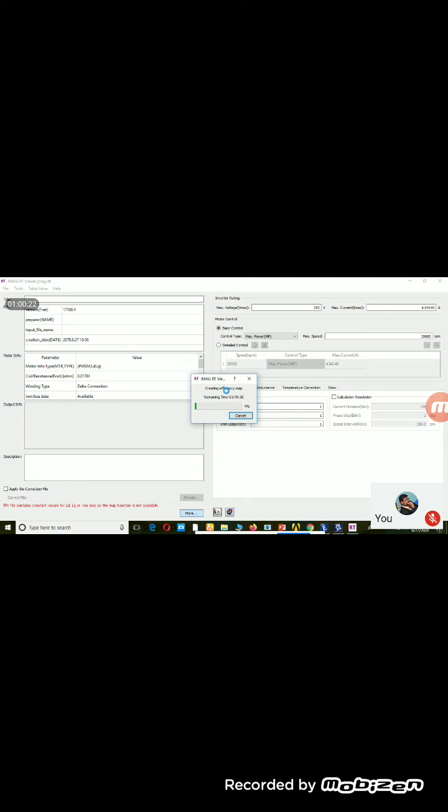For any electric machine, just go for ANSYS packages for the thermal analysis as well as the vibration analysis. Don't go for some other package, because it may take more time, and the accuracy is also high in ANSYS, and it is user friendly for structural analysis. Whereas for electromagnetic analysis, ANSYS is a difficult one.